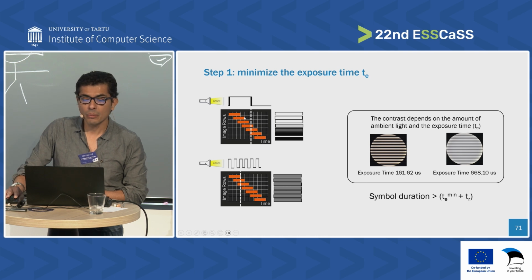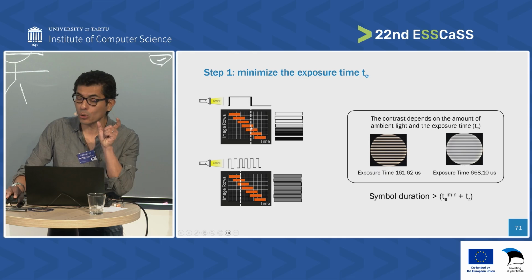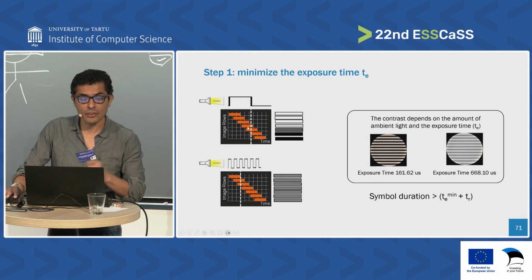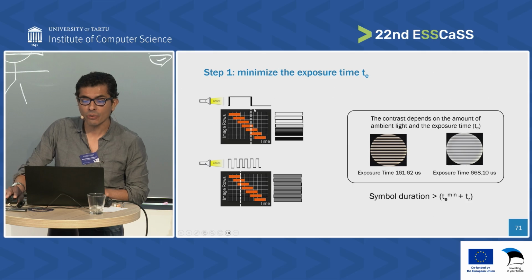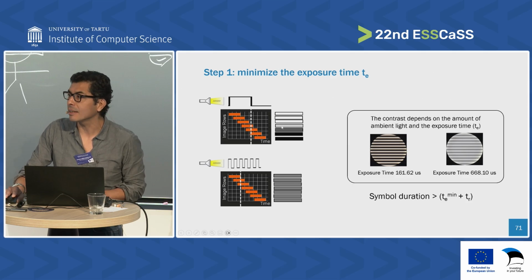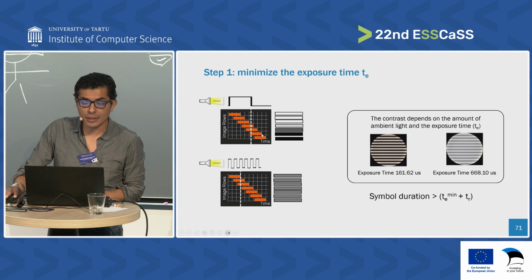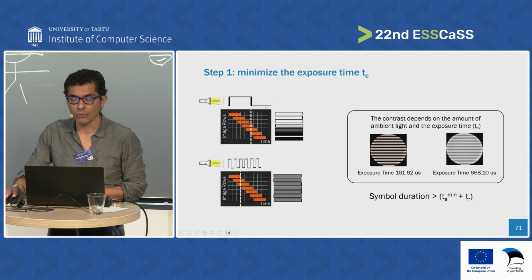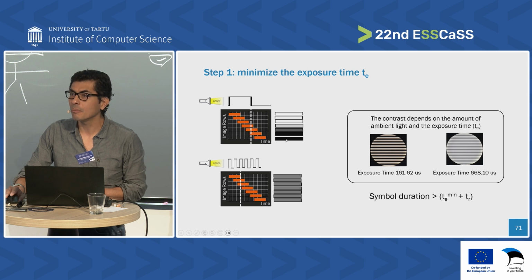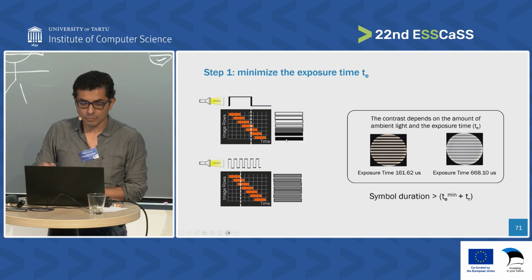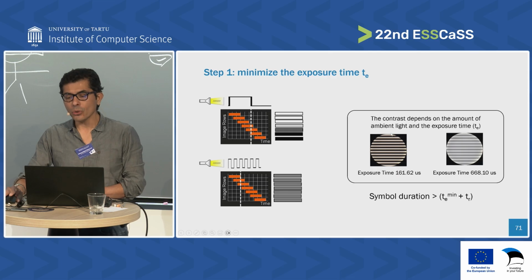It comes the second row. It still sees that it's during the time where the LED is on. And we continue like that. Look what happens by the time that we reach the fourth row. By that time, let's say around 80% of the exposure time is when the LED is on, but the remaining is when the LED is off. And that's the reason why this appears like a light gray. You continue doing this, and at one point there are going to be rows that are completely in a position when the time is off. And hence, you obtain these dark points. That's the basic idea. So in that way, you can create these patterns.